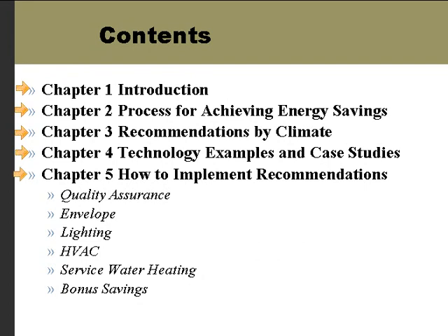And again, we're dealing with lighting in this talk today. When you get to chapter 5, the lighting section, there'll be all these how-tos. Some of them will deal with issues around daylighting and how you would bring daylighting into a building, or occupancy sensors and what type of occupancy sensors you should look at using, or how you would meet the lighting power density recommendations in that climate zone table.